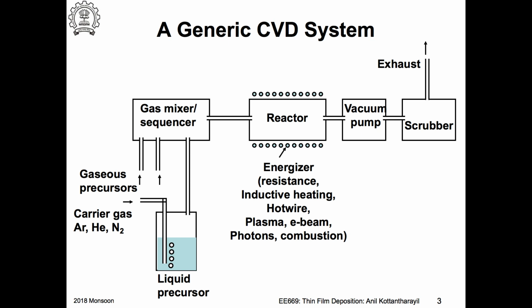And then, you can have a liquid precursor. Yeah. So I need to convert this into vapor, okay. And you can also have a solid precursor in some cases, so we'll discuss that later on. But there are certain requirements for the vapor that goes in. So what should be the partial pressure or vapor pressure of this material that goes into the reactor is important. So you use a bubbler arrangement, which we have already discussed in some previous lecture, right? You have the precursor and then you use a carrier gas. So this is typically something that carries the vapor.